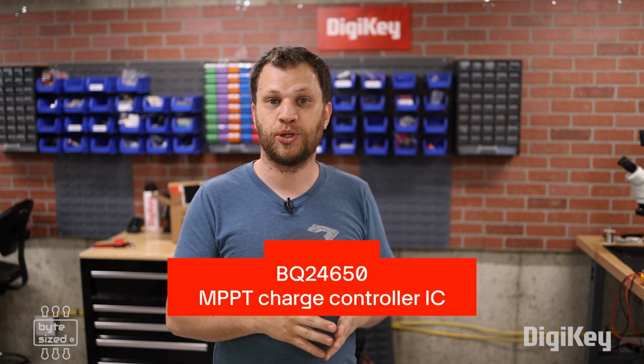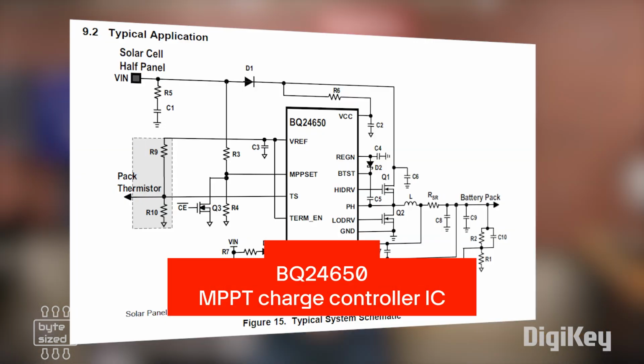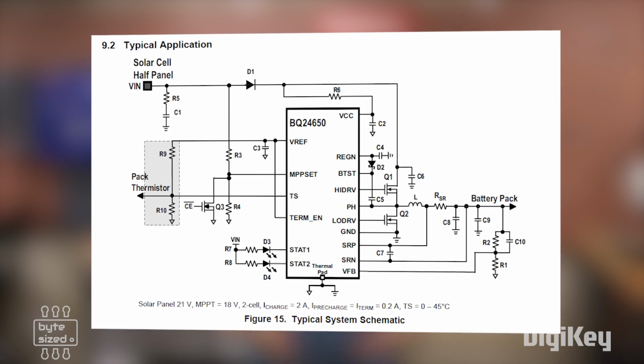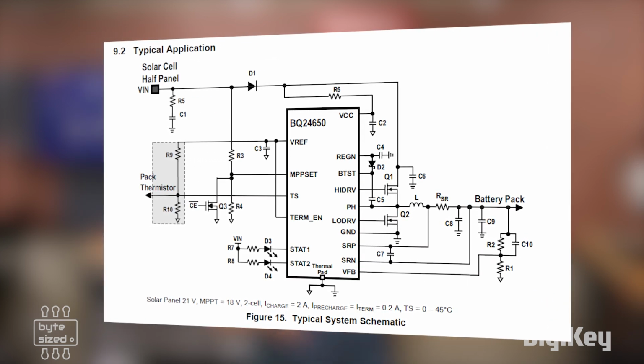The chip that I'm going to use to design my own maximum power point tracking charge controller, that's too much of a mouthful. From now on I'm just going to say MPPT, maximum power point tracking. The chip that I'm going to use for my MPPT controller is the BQ24650. I opened up the data sheet and I found the typical application circuit, and at its heart it looks very much like a buck converter with a few extra parts. From there I can just use the typical application and design my own custom PCB.